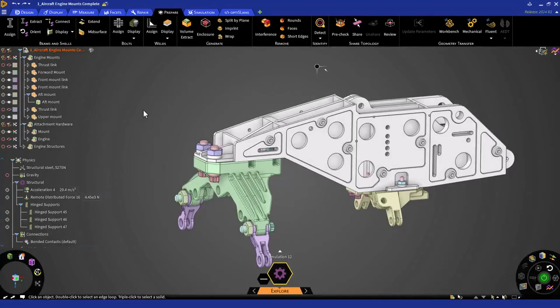Let's start by assigning bolts within the model. The bolt idealization tool allows us to create beam element representations of bolts to aid in the setup and solve portions of our simulation. Currently, the bolts are being modeled as generic bodies, but assigning them bolt properties will later allow us to report bolt-specific performance results. Additionally, we'll be able to reduce memory allocated for bolts and increase the speed of our simulation by following this